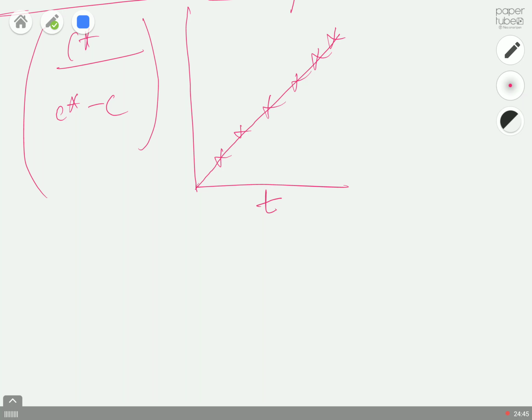It should pass through the origin 0, 0, and whatever slope you get will give some number that reflects how fast your oxygen is transferring from the gas bubble to the liquid phase via the interfacial area available per unit volume. So the KLA value should be really high.